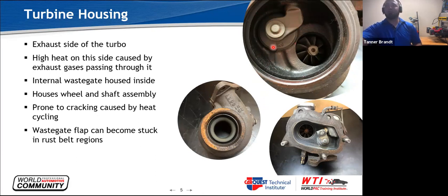So a lot of people think that that crack means that's bad. That crack will show up about probably a month into a turbo's life. So the crack is not a sure thing that it's bad. It's pretty typical of most turbos. When that becomes an issue is when that crack starts to open and you start seeing chips out of it. So you can see this one is a pretty uniform crack and it doesn't look like there's any chips missing. It's spreading a little bit up there.